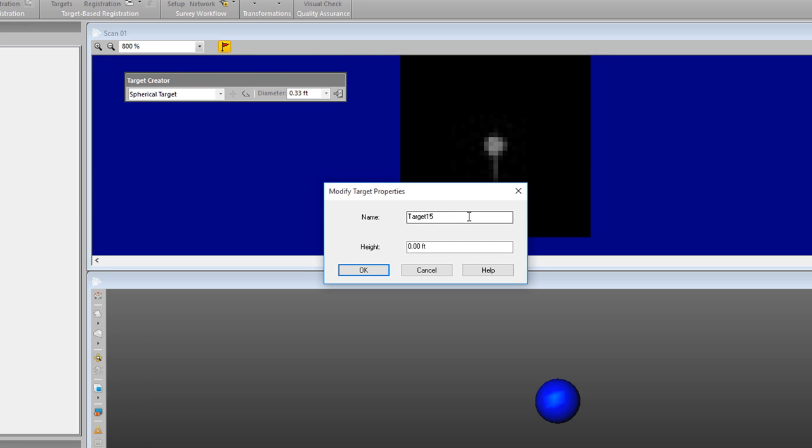They're all just targets, but again, for me to keep it straight in my mind, I like to refer to it as my back sight, and I'm going to call this 000 because it's behind my station 1. Makes sense to me. And then I'm going to put in the height. So I used a height of 5 foot, and I find it easier just to highlight over the entire field and then just click number 5 and then hit enter. And I'll go ahead and put that in there.